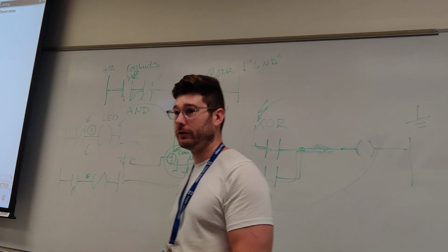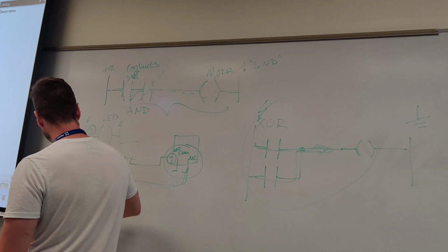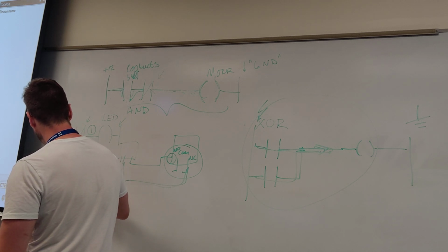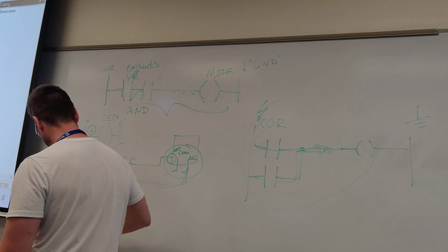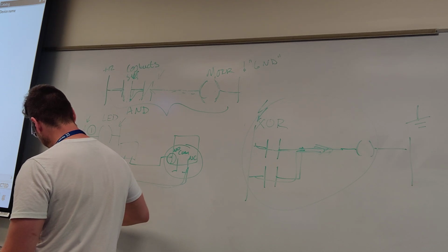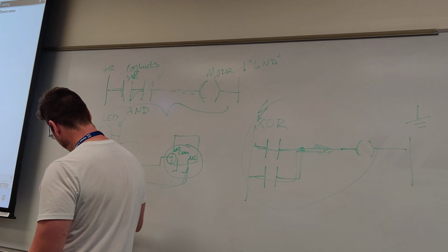The ladder logic for that would be this. If we have a sensor up here, monitoring to make sure that we aren't overflowing, when the water's all the way down here, this sensor reports 0. When the water's up here, this sensor reports 1.